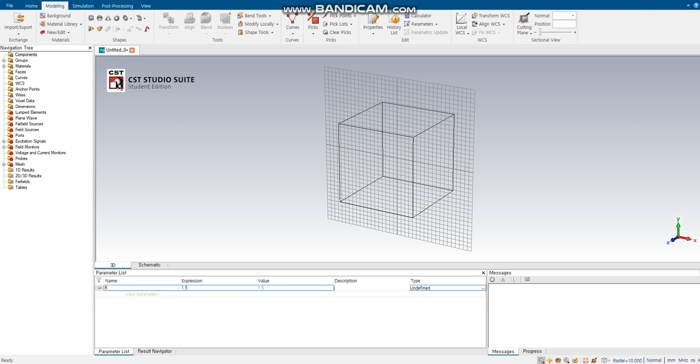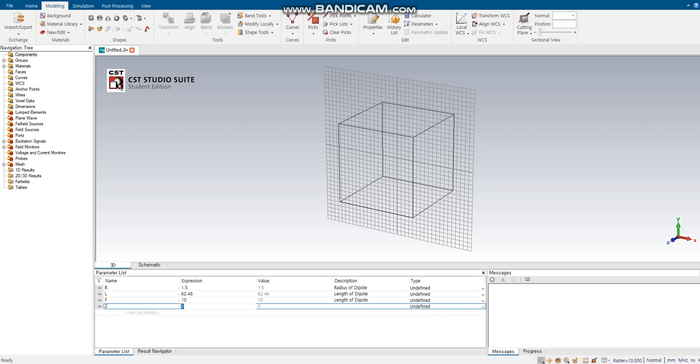Okay, it's finished. So let's check the S parameter again. Here we got our new S parameter. After zooming in, we can see the antenna will resonate at 2.4 GHz exactly. That's what we want. We can change it to linear, then mark to check the return loss here.